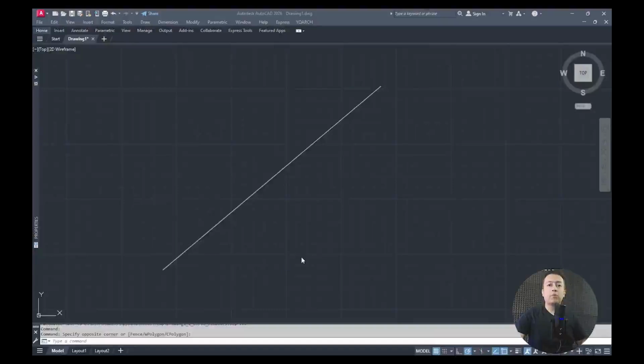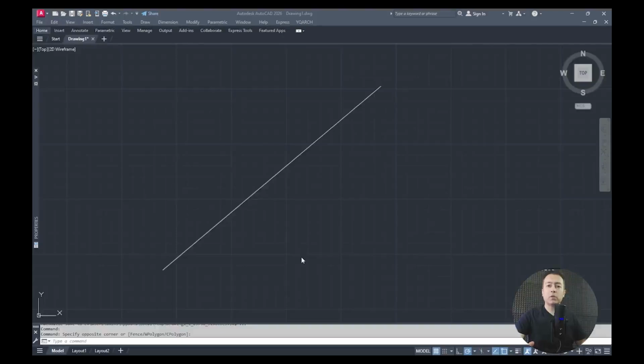In the previous video, we talked about units in AutoCAD, and here we want to talk about measurement in AutoCAD. Basically, we have two categories of commands: measurement commands and dimensioning commands. Each of these serves its own purpose. With measurement, you can determine the size of an area, and with dimensioning, you can print that measurement on your drawing. We will talk about dimensioning later. Right now in this tutorial, we are going to discuss measurement commands.